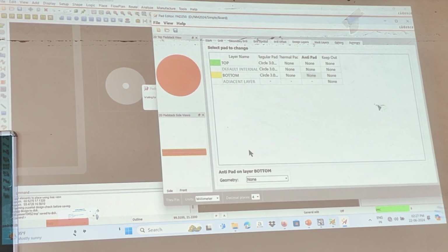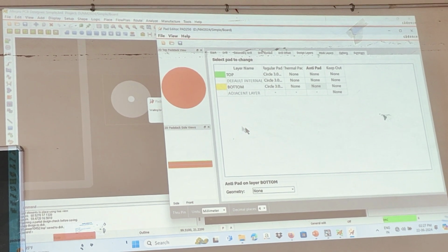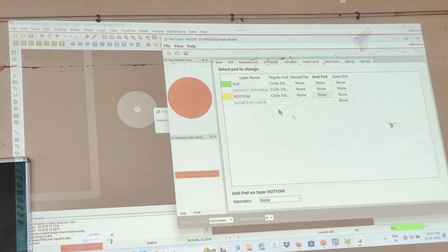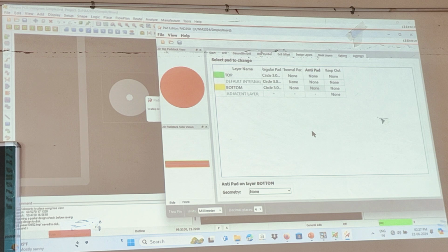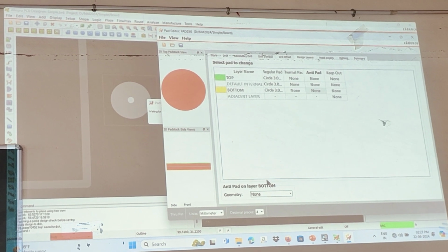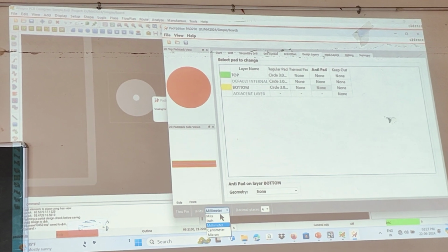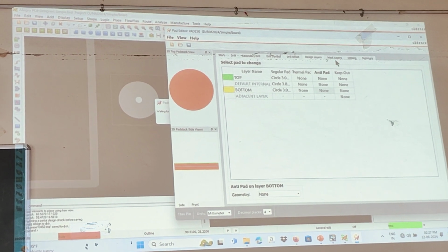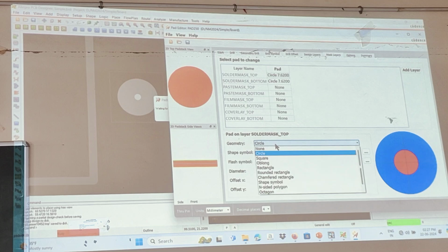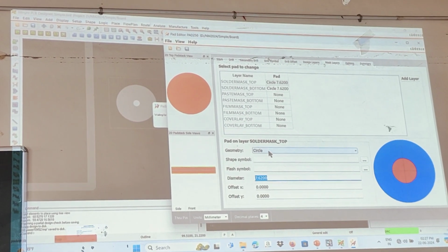This also we no need to do every time. We can create a pad in such a manner that a 3 mm drill alone is there, and we can save it in our footprint location and use it regularly. And here also we have to check one thing, there are units, we have to maintain that. Next, mask layer. No need of mask layer.